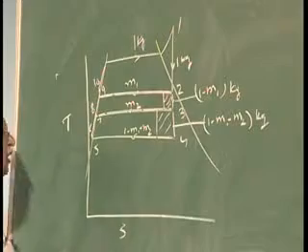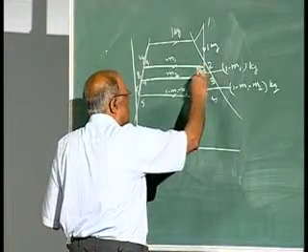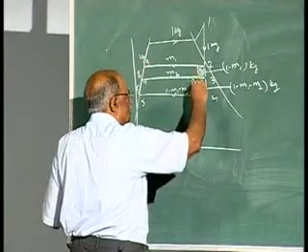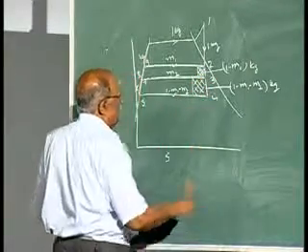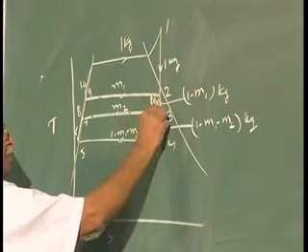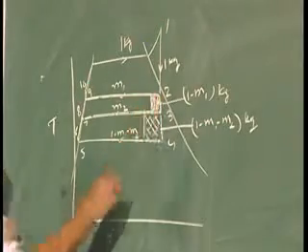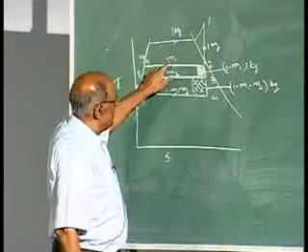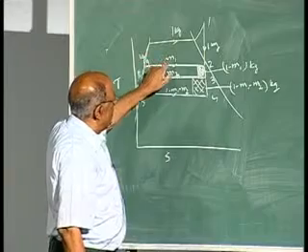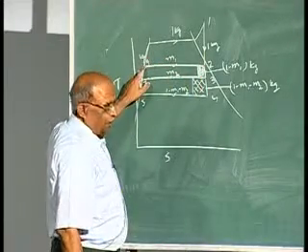These are the specific enthalpies, and to find out the quantity of work that is being lost because of this regenerative feed heating, this area has to be subtracted. This area corresponds to the heat of the mass that is being extracted. This is M1 and this quantity, 2 to 9, is for 1 kg.